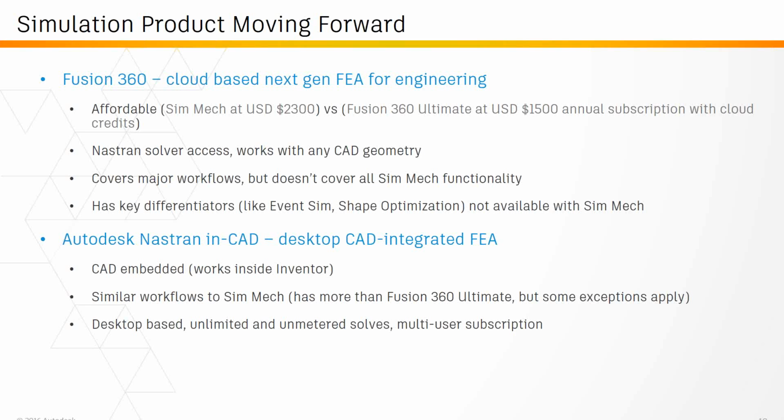And then we also have the shape optimization available inside of Fusion 360. So again, you apply this load, you have these constraints on it, and you want to see what's going to be the best shape, what material can I remove to get the best design for this.